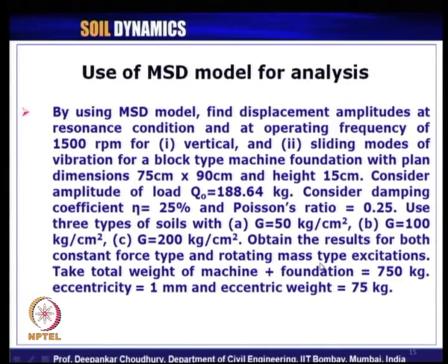In our module 2, that is vibration theory, we have seen for the mass spring dashpot model, for any machine foundation, we can have two cases. One is when the machine is subjected to a constant harmonic load, so that is called constant force type machine foundation, and another is when there is some imbalance present in the system. Because of some rotating component, we can also get a dynamic load on the system. So for rotating mass type excitation also we need to find out the displacement.